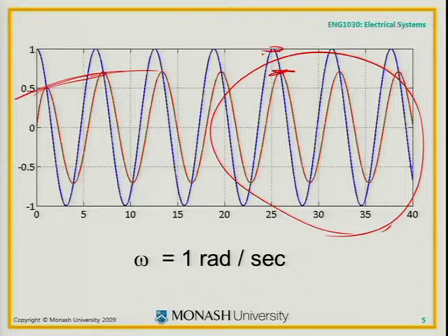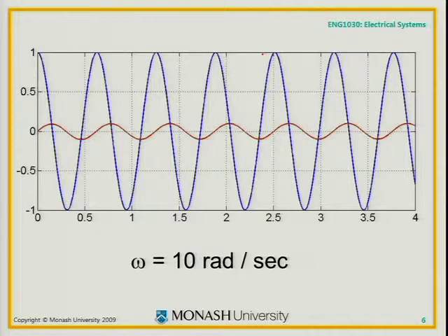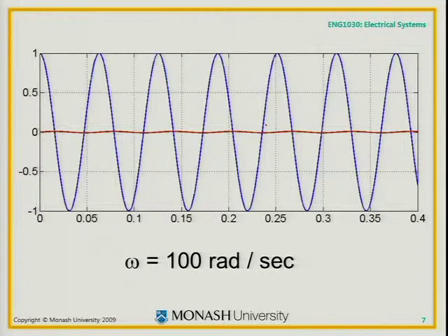So we see a couple of things there. The transient behaviour, we know what the steady state is. We're looking for sinusoids. And in that case, that's what the amplitude is of the red. So that's our output voltage for 1 radian per second. Let's up the frequency. There's 10 radians per second. You can see the voltage on the resistor has dropped considerably. It's down here now. What about at 100 radians per second? Well, 100 radians per second is not really getting through. 1 radian per second gets through with good gain. Certainly by the time you're at 100, there's only a tiny little ripple there.